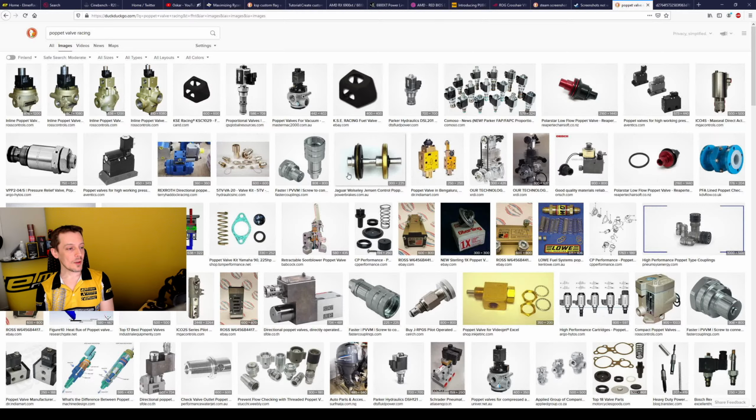So yeah, with these industrial type valves, if you need something to seal very well, then that's reasonably easy to do with a poppet valve while maintaining very high pressure ratios. It's going to have high sealing forces, or high pressure forces, that are able to create a really good seal. Of course, if you have particulate matter that you're trying to seal, then poppet valves are not very good. So then you need some kind of different valve system.